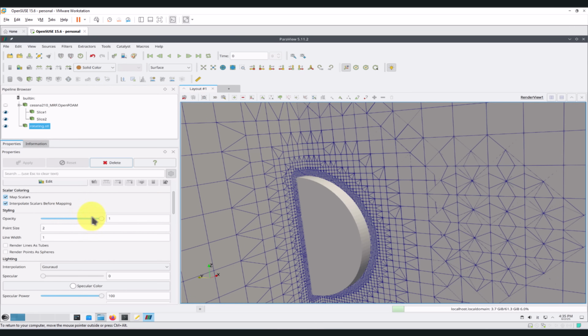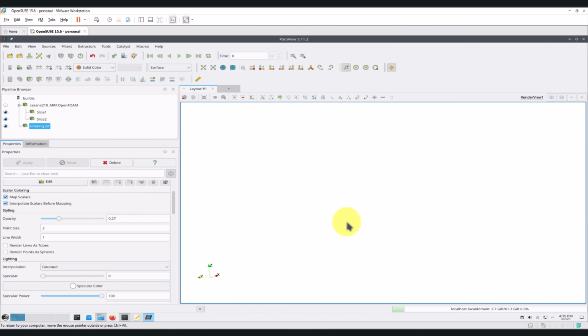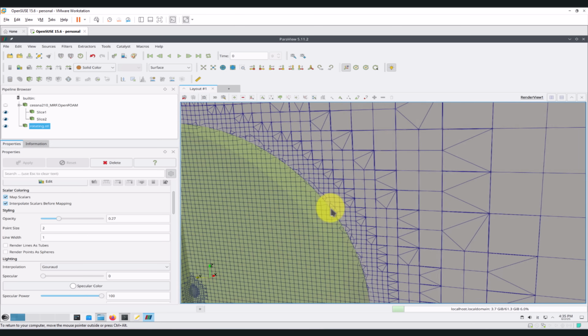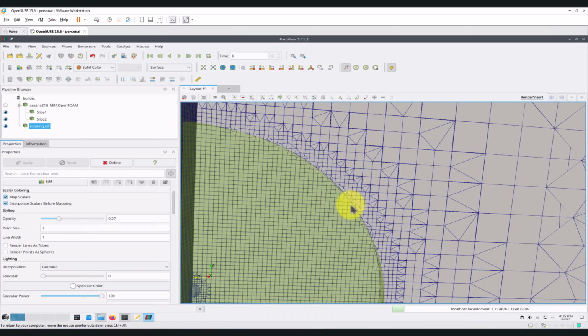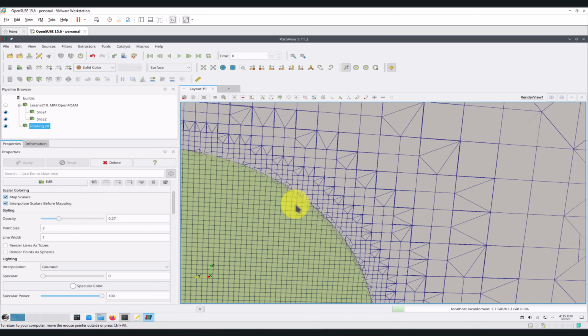So this is the cylinder, the surface that we're using now to create that region. You have it there, okay? So if I zoom in there, look at that. It is not perfectly matching. So remember the issue with the boundary layer, some collapsing, and this is tricky to control.